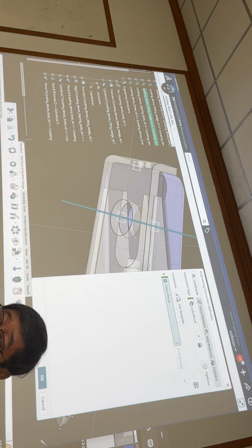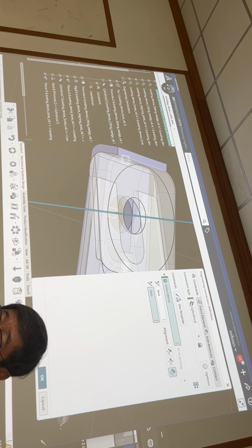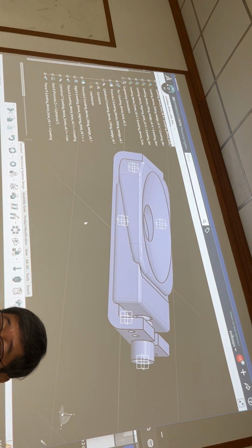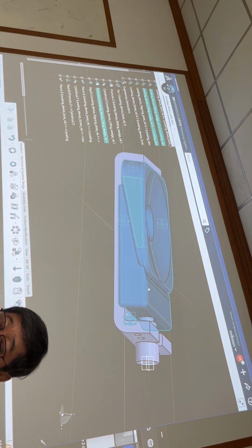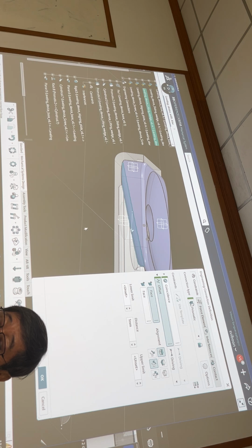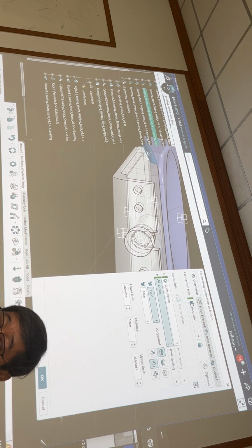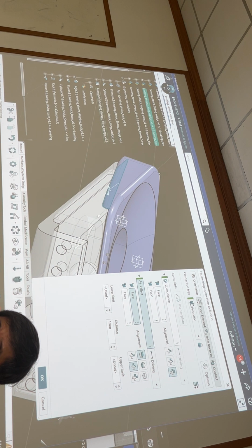This hole and this hole align. Okay, and then the other one is also prismatic between these two. These two are prismatic as well, only with an offset distance. Prismatic face to face, with a distance here of 1 mm as well. Coincident, the two faces, the top face with the bottom face. Okay.